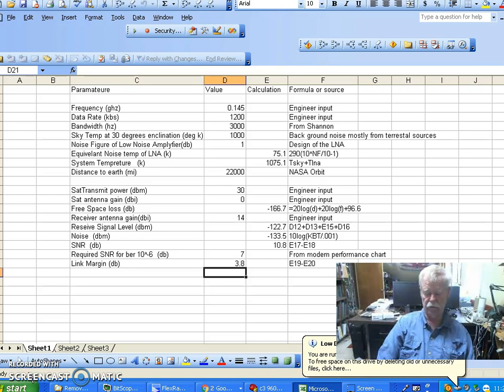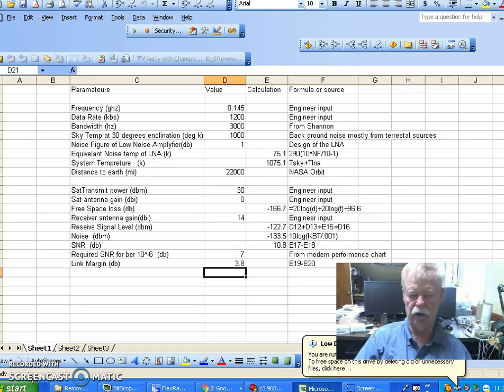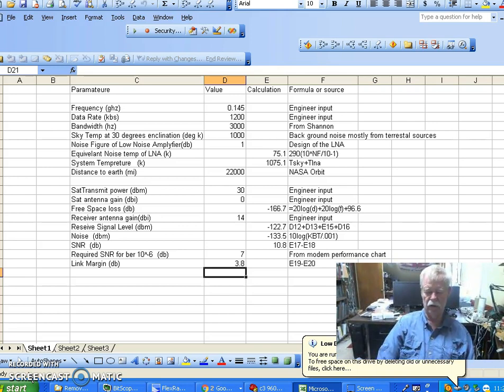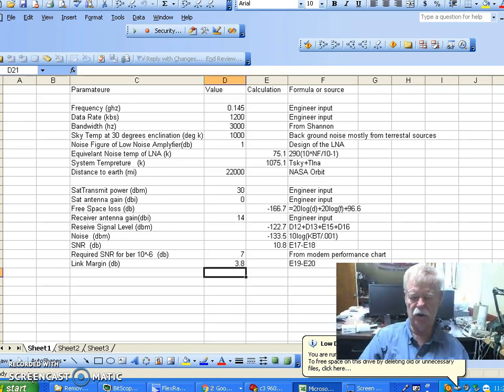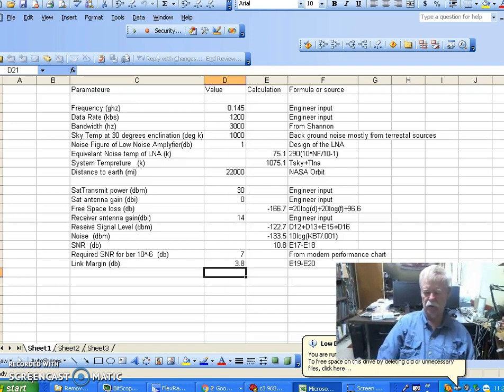It turns out, again from experience, 1 watt is achievable. And because we're satellite engineers, we tend to express most of our measurements in dBm. How to get there is beyond the scope of this video. Simple logarithmic math. So let's start out with 1 watt, which is equivalent to 30 dBm.